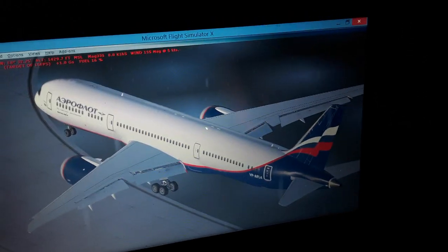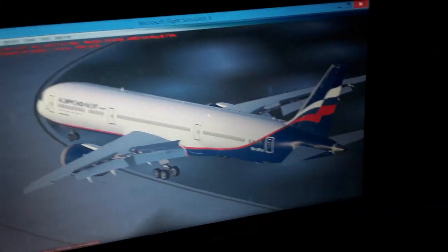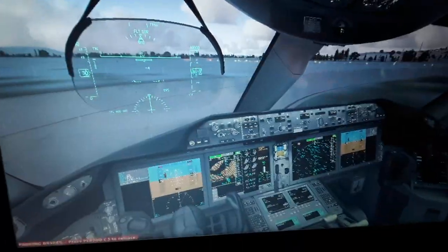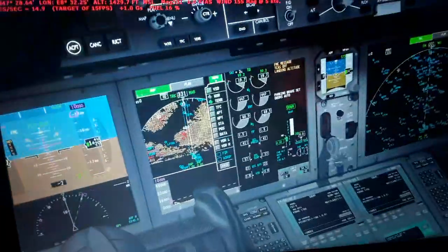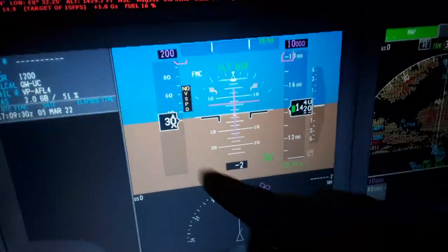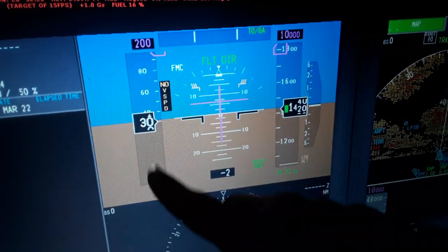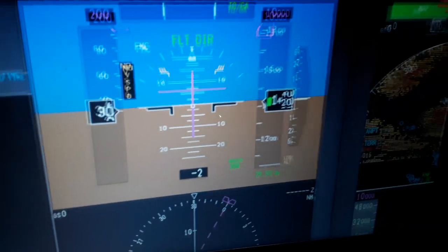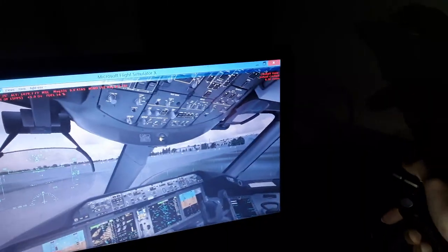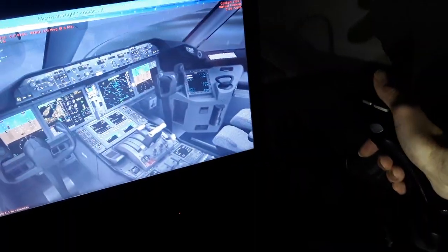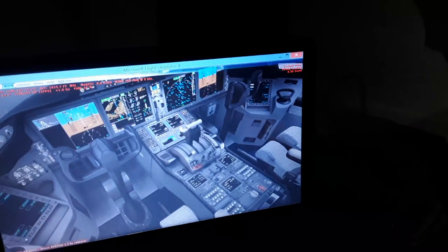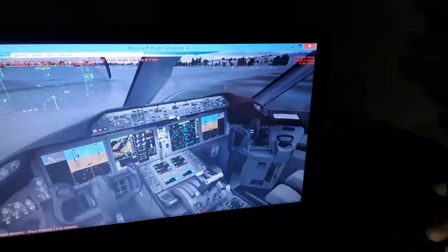So when flying, we monitor here the airspeed, the primary flight display. We can see the airspeed indicated over here. Just below the airspeed, we will see the stall speed with an amber and red warning indication. We need to avoid that. We need to overcome the stall speed and the angle of stall. So we push the yoke of the Boeing aircraft down, or the side stick of the Airbus, and we apply more thrust to make a stall avoidance maneuver.